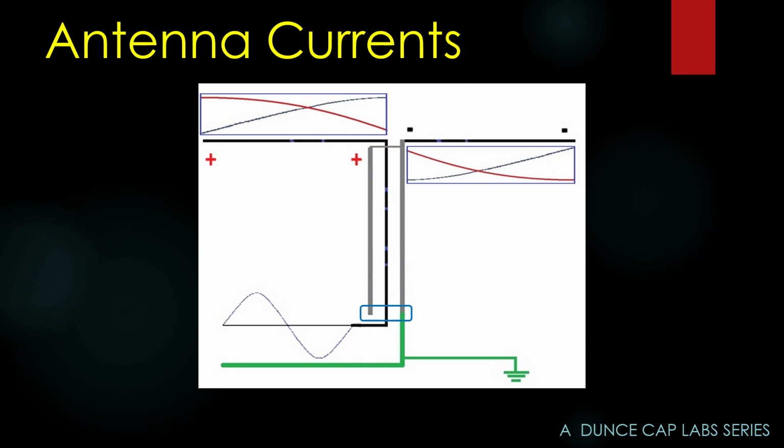The way we do that is we introduce the one-to-one balun transformer. That way, like all transformers, each side can do its own thing and energy is transferred, and transferred well. So this is the right way to do it, and it solves that imbalance problem because now the shield connected half of the antenna can swing in voltage without any problem because it's no longer physically connected to the shield going back to the station.